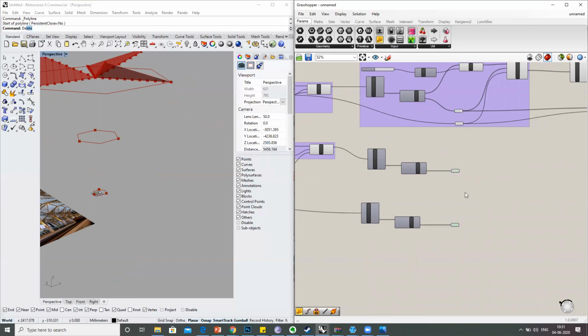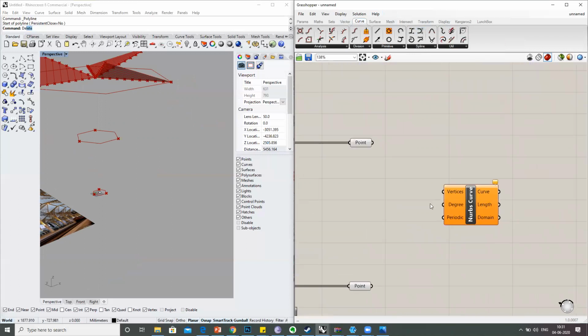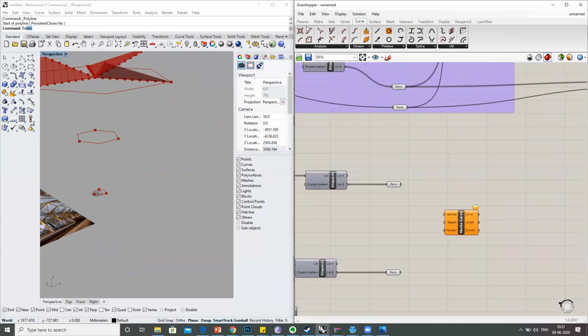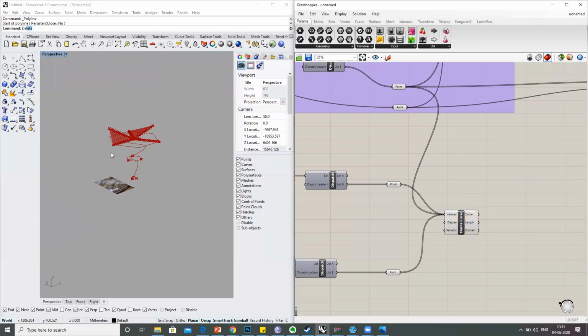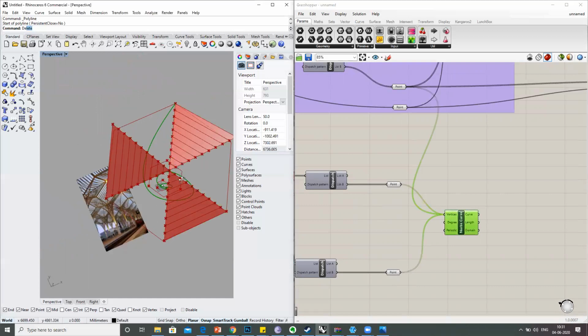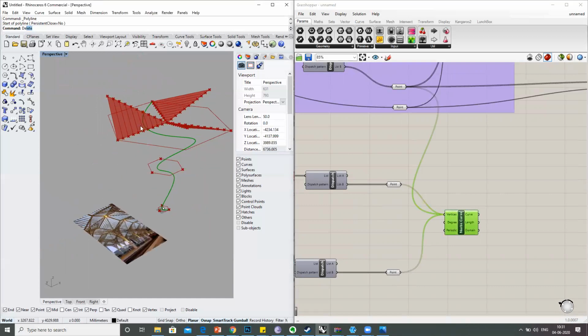Now I just have to interpolate a curve. So instead of interpolating, we'll just use a spline curve. So in curves, you can use a NURBS curve. So I just have to plug in my vertices. But before plugging into the vertex, I can teach it to you with the reference itself. So if I connect all these together, you'll see that the curve spirals down. So all these points are getting weaved together.